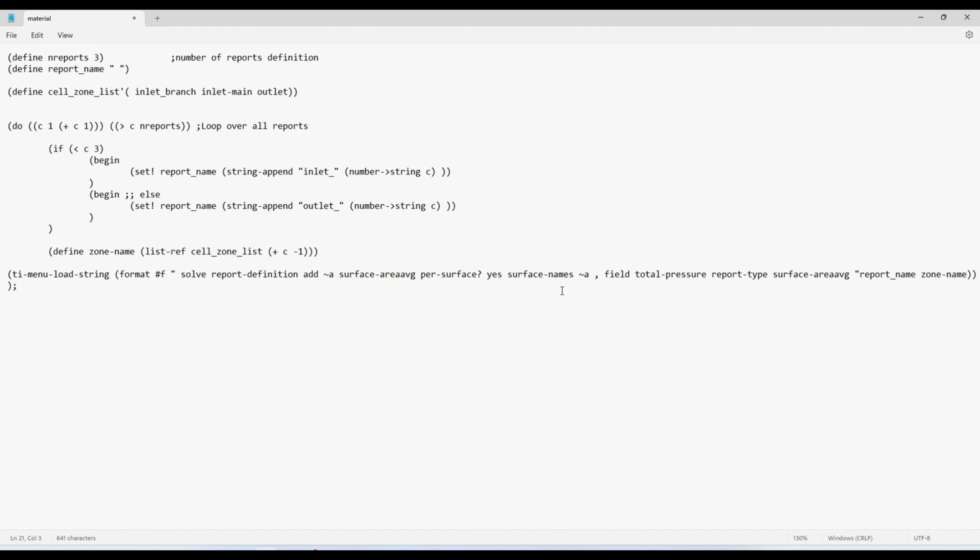And then we have over here comma. Comma is used when we are writing some command, and sometimes we hit enter or we accept the default condition. So this comma is used to accept the default condition. And this entire thing is used just to write this entire command in a single line as a string. This one is just formatting. There is nothing special. It's just a way of writing this entire command.